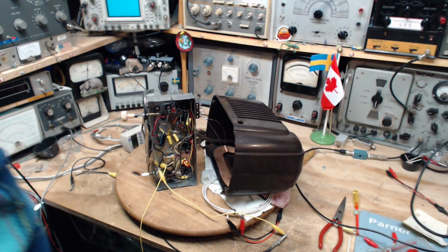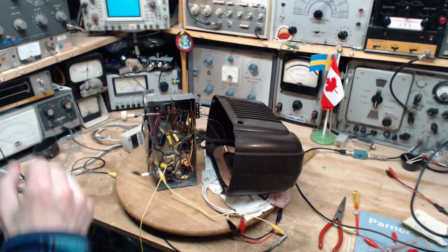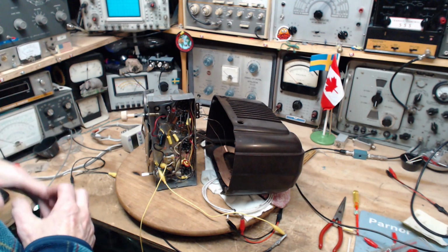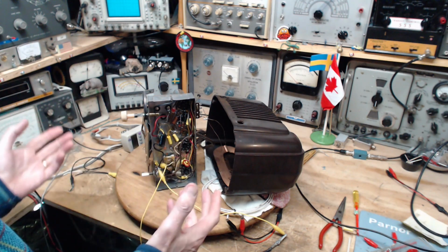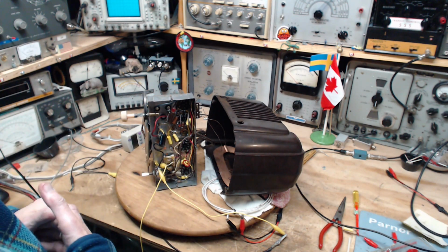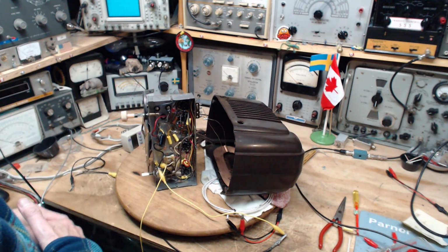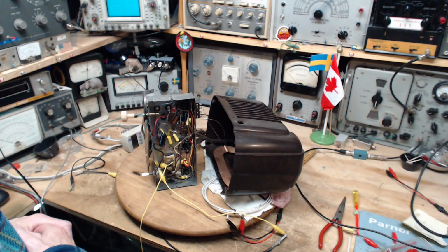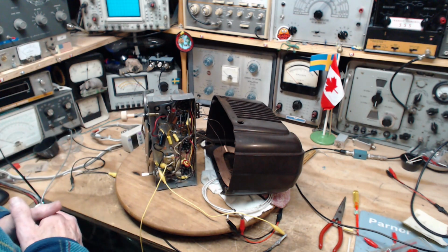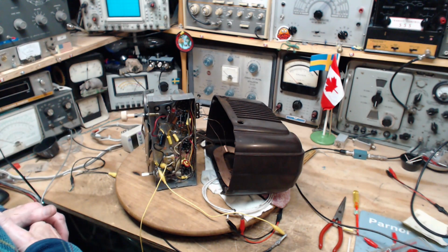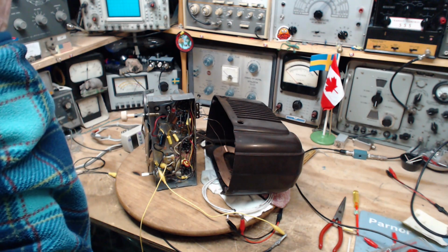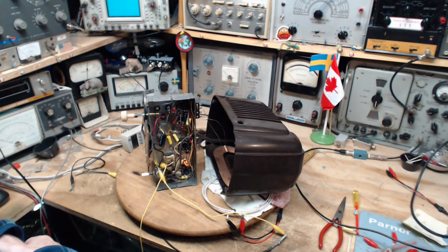So here's my idea. I'm going to use the SDR with a pickup coil to try to pick up this, let's call it phantom signal, phantom oscillation in the IF of the radio. Get it visible on the SDR, and then fiddle with the alignment, with the adjustment of the IF, and try to see if I can knock it out. Or knock it down, I guess, to the point where it's not loud enough to be a concern. I don't know, that's the best I can come up with.